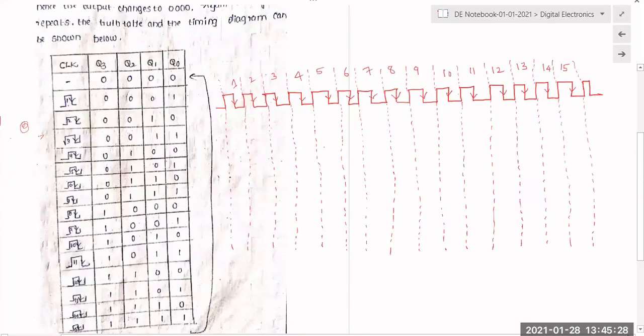Yeah, this is the truth table of a counter in which we are applying the clock pulse. Whenever I apply this CLR prime, clear prime, then all the values are zeros. And whenever I apply the first negative edge, this is 0 0 0 1, because 0 to 1 will be changed. 0 to 1 is positive edge, so no change. So 0 0 0, because the first output will be acting as a clock pulse for the second. So first output is changing from 0 to 1.